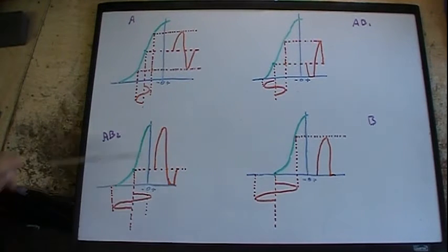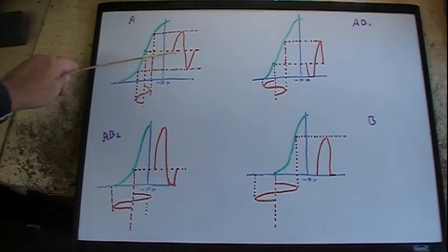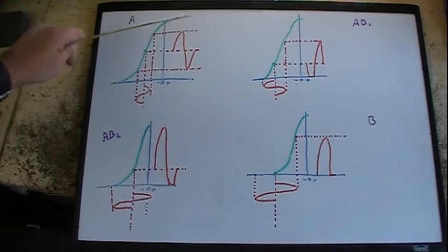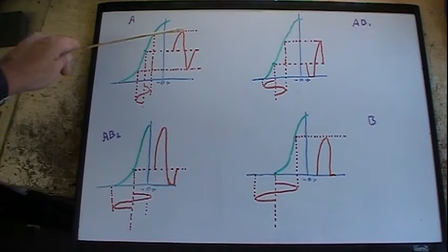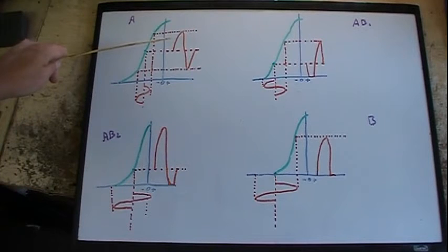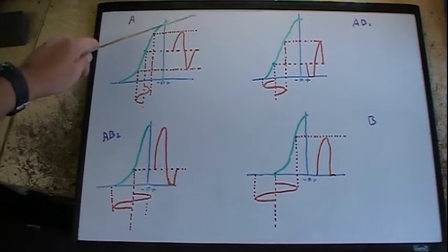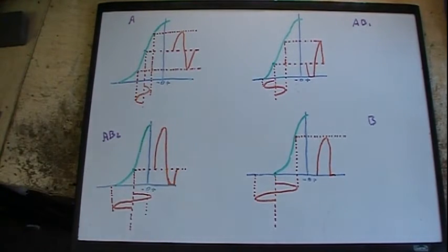But that's Class A. It's the least efficient. It is also the least powerful. It's the least on an amplification range, so it has the least gain. They still amplify really good, but of all the amps that I have represented here, it's the lowest power output. But it's got the best fidelity output because it has the least amount of distortion.